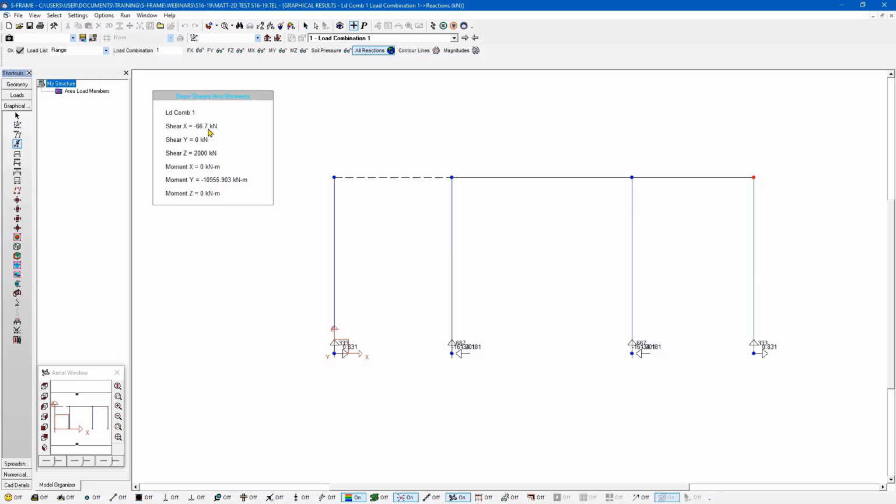Well, what happened was that the solver was able to identify that this is a non-gravity load combination, and because the lateral loads exceed our notional loads, it's just going to apply the lateral loads themselves. And that's one of the processes described in Appendix O.2.